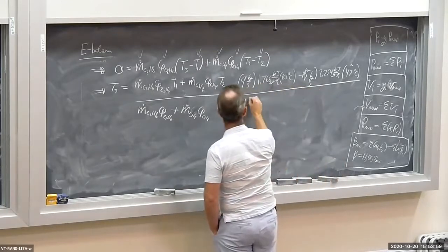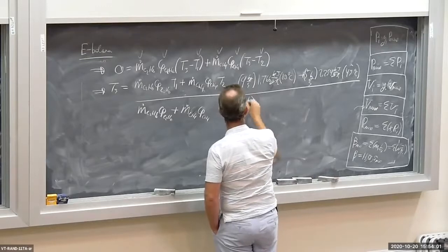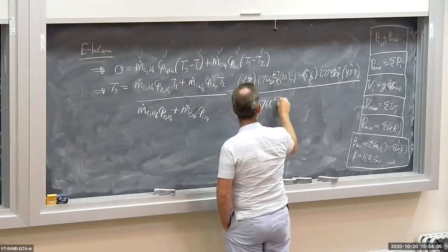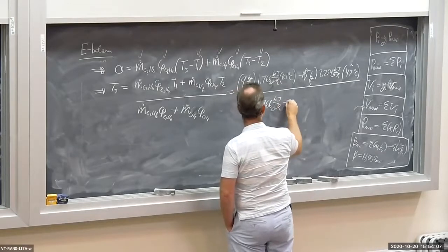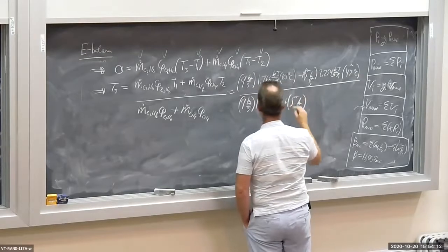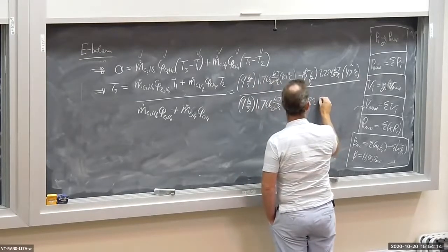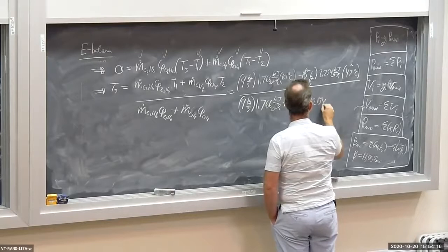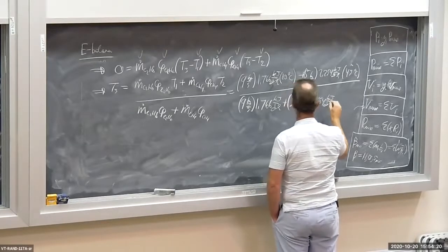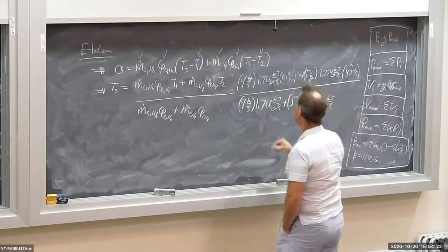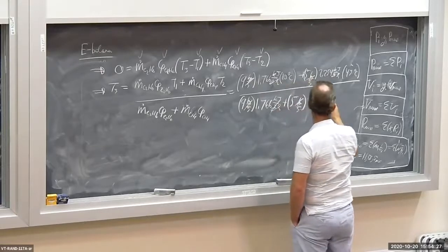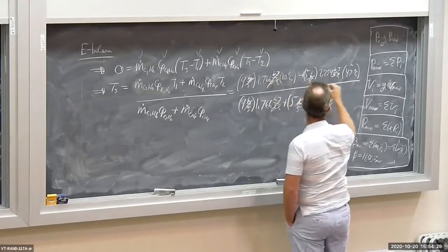So now I have 9 kilograms per second, 1.766 kilojoules per kilogram degree Kelvin, plus 5 kilograms per second, and 2.254 kilojoules per kilogram degree Kelvin. Let's look at the units here. The kilograms per second all cancel out. The kilojoules per kilogram degree Kelvin all cancel out.